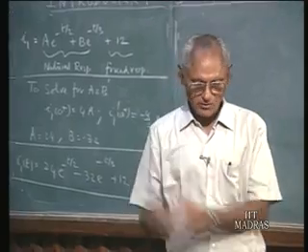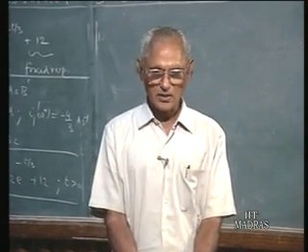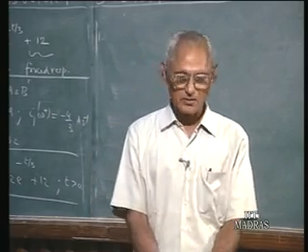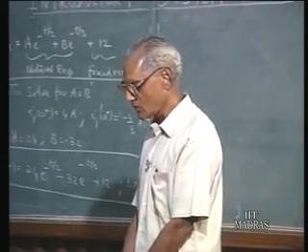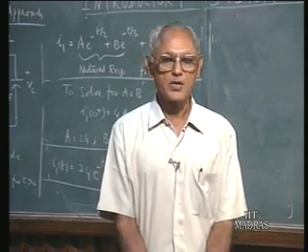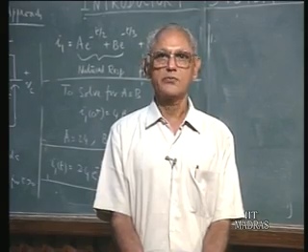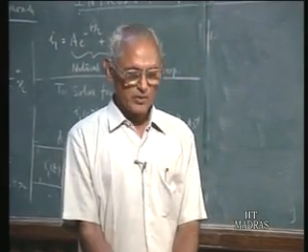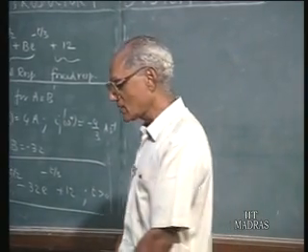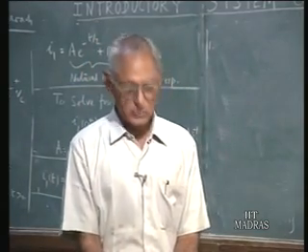They are in general complex. In our particular case, it may have been real, but in general complex. So these complex frequencies present in the source free response, the complementary solution, are called the natural frequencies. This is characteristic of the system. It does not depend upon the particular forcing function. On the other hand, the particular integral solution is what is called the forced response part of the solution, and it has all the frequencies which are present in the excitation function or the input function. The sum of these will be the total solution, and in solving for this we need to have information about the initial conditions of the quantity which you are going to solve for.